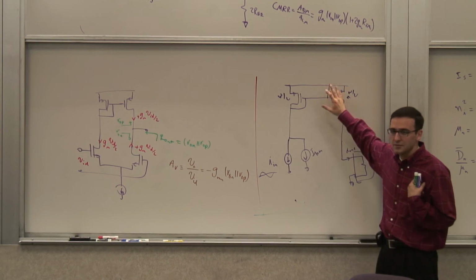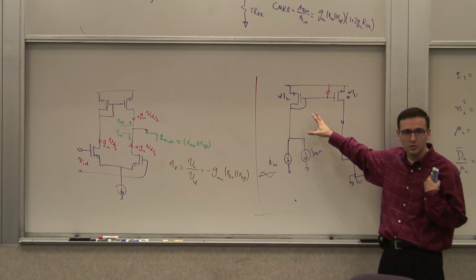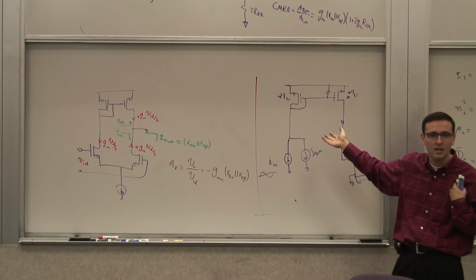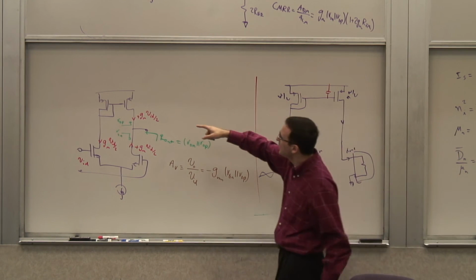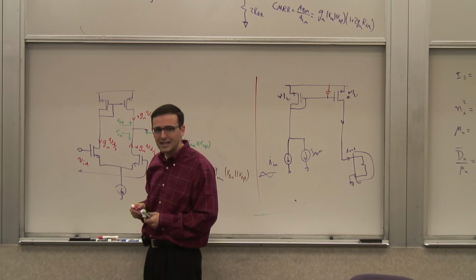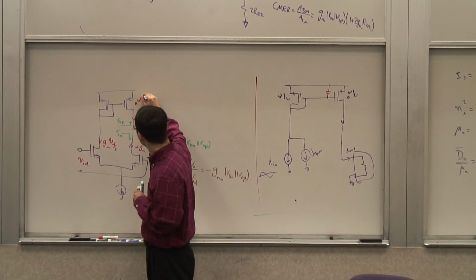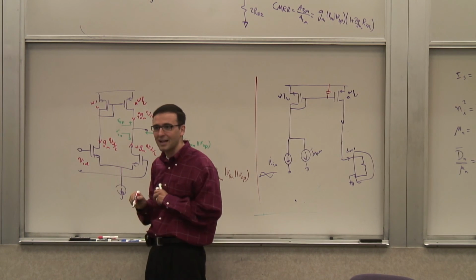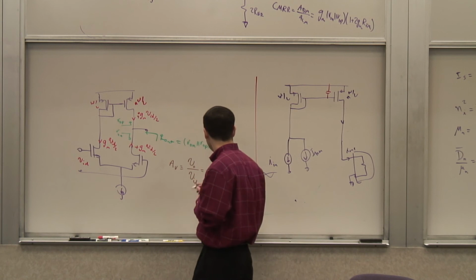And again, we'll talk about this frequency response extensively next quarter, but I just wanted to give you an idea that this is not completely free. So what we did here, we did a current mirror, so we did a one-to-one. Somebody may come back and say, why didn't you do an N W over L here? Because in that case, this would be N times that. Right? So this, instead of this, becomes